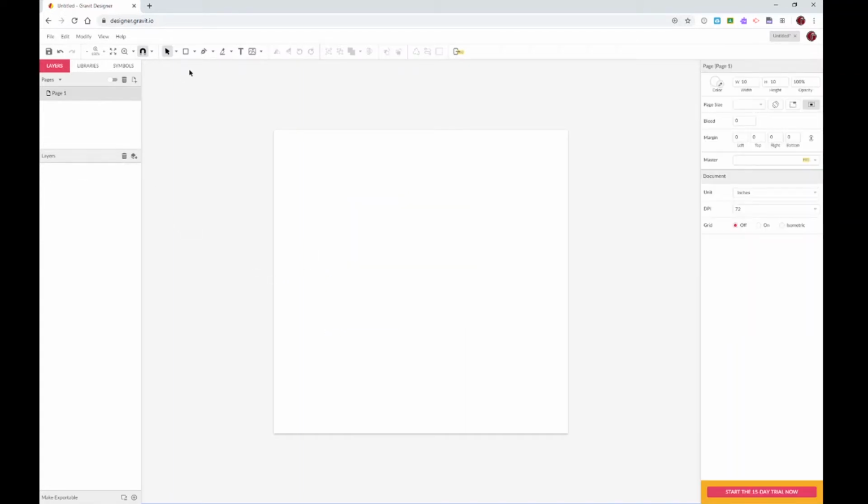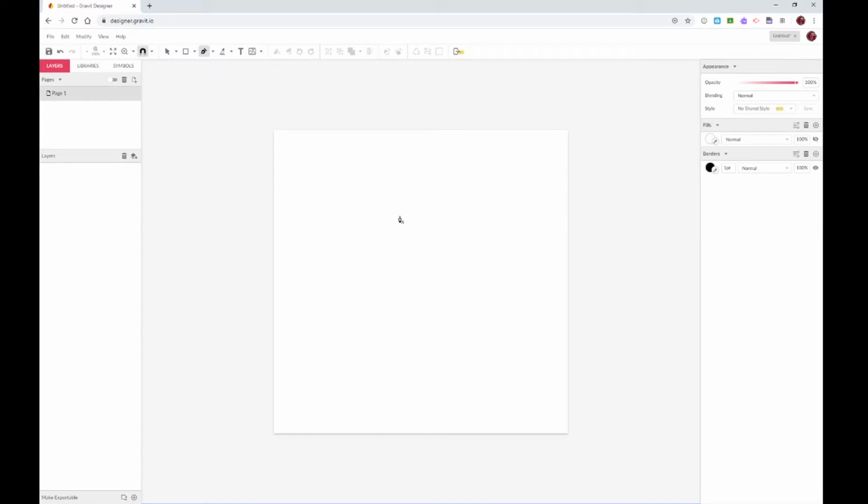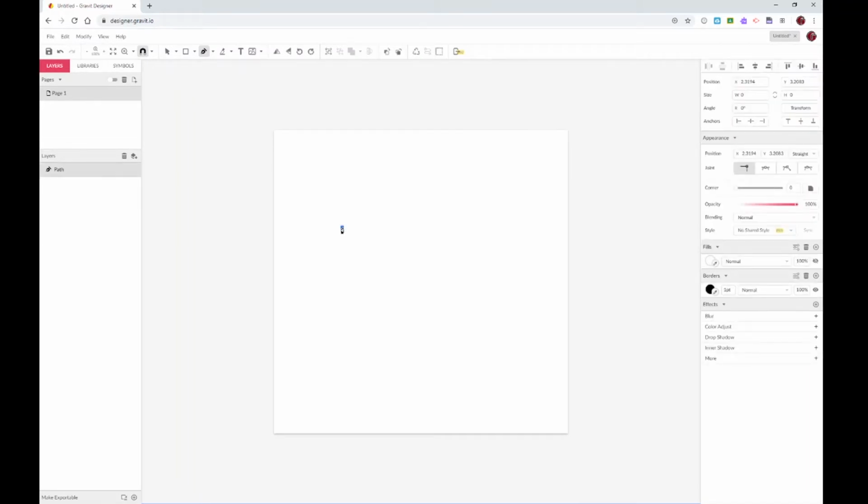When you have a pen tool, your pen tool creates anchor points. So if I'm going to make a rectangle, I'm going to click once, click and release. And now I've made an anchor point. And you see that there's this line extending away from it. I can click and drag and make my next point, which I'll make down here. I'll click and release. Clicking and releasing is really important because that allows me to have a straight line coming out of my anchor point. I'll click and release again. I'll come up here and see how it kind of locks straight for me. It even gives me a guideline to make sure that I'm going straight.